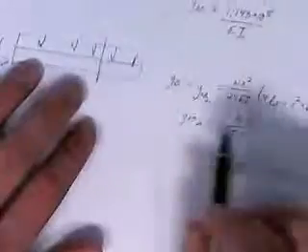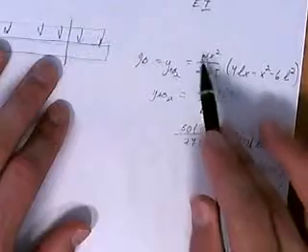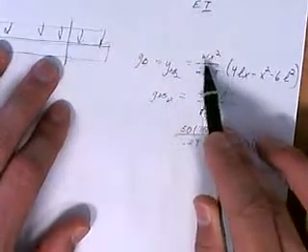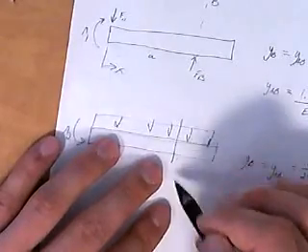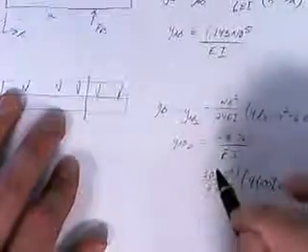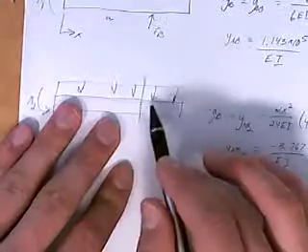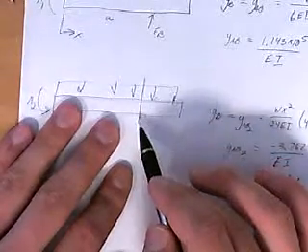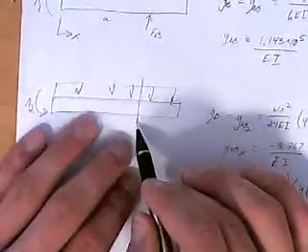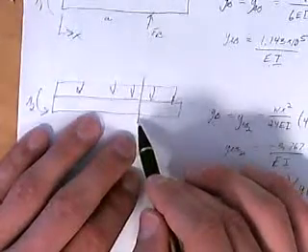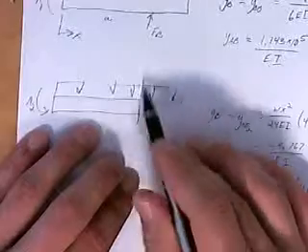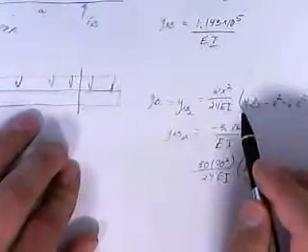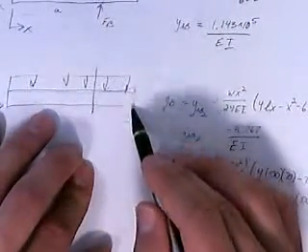In this, the distributed load is pretty easy, but it's mainly the split right here. When you're using this equation, X is equal to the place right here, because within that equation you have to define X at the point where you want to know the displacement, especially for these distributed loads. We want to know the displacement at this line, so we make X 70. If we wanted to know the displacement at the end, then we'd make X 100.